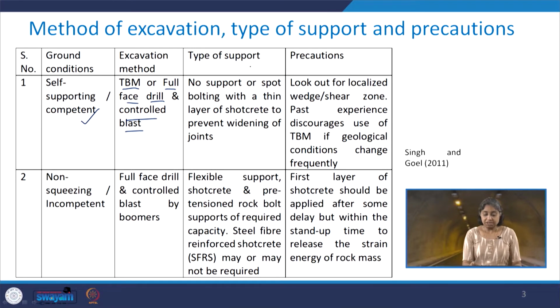In case of the type of support, in the previous class also I mentioned that for the self-supporting or competent type of ground condition, basically no support is needed, or sometimes spot bolting with a thin layer of shotcrete is applied to prevent the widening of joints which may be there because of the excavation process.